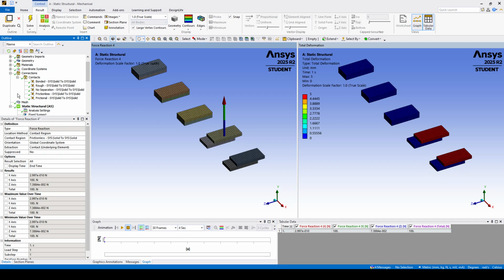In our case, if we go and see the reaction force, you can see that I have a reaction force up with 100 Newton, but I also see around 19 to 20 Newton as a resistance force in the counter direction. As you can see, the direction of my reaction force is in comparison to the side in which this top plate moves. And this is the frictional contact.